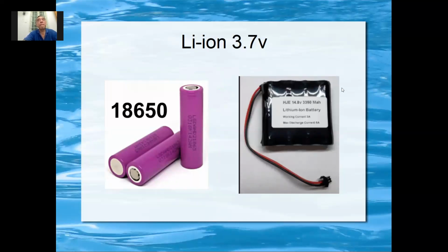But it's just a dimension. Most of the time it is replaceable. You can use either lithium ion or lithium iron. The full name is lithium iron phosphate, because the difference is 3.7 and 3.2 volt. A lot of devices will be able to absorb that small difference in voltage.